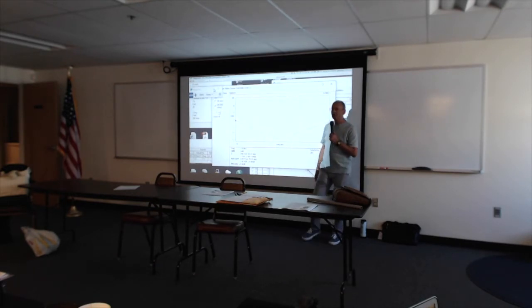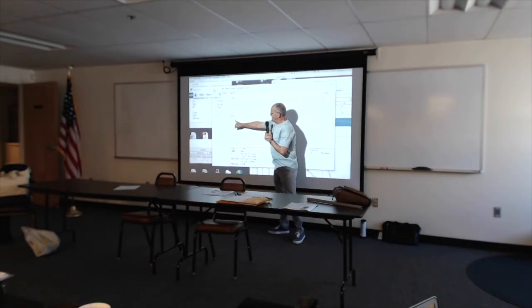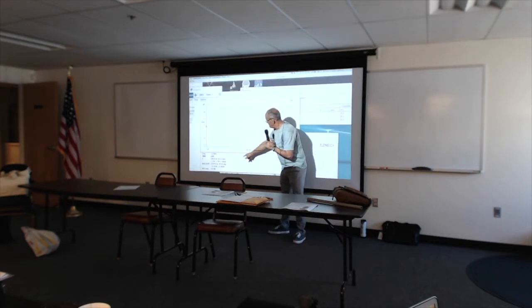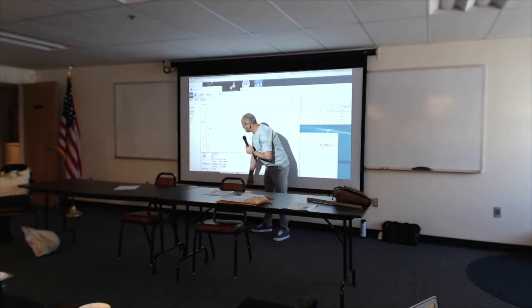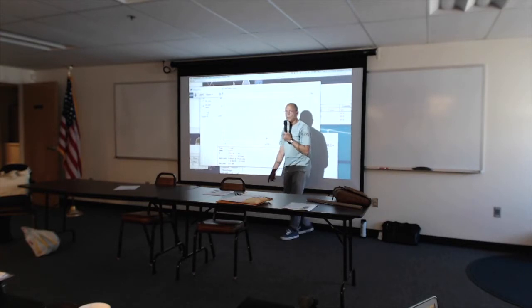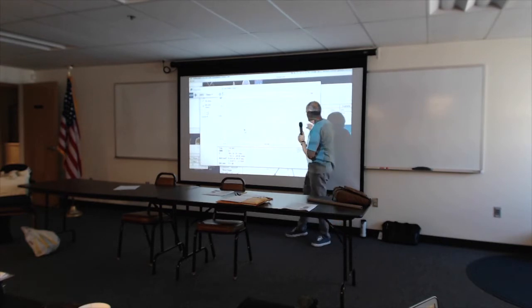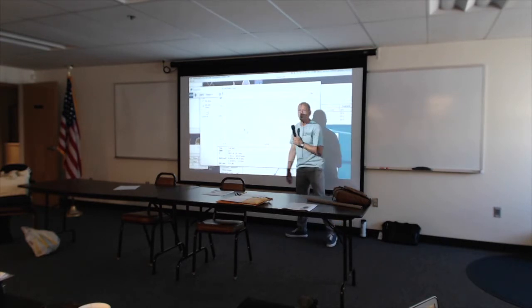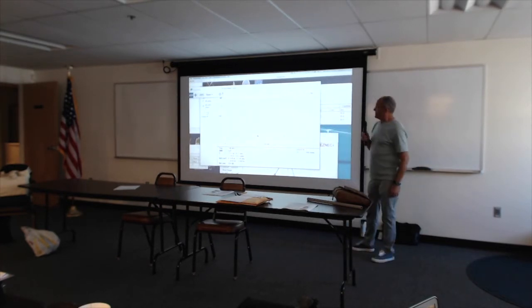Middle of the band. Yep, that's great. If you move this little dot here, you can see it'll update this information down here. Right now, there you go. So now we're at 1.9 megahertz, and the standing wave ratio is 1.14 at that frequency. You can continue to move that little green dot along this line, and you can monitor that to see how to adjust the values. So that's an SWR plot.